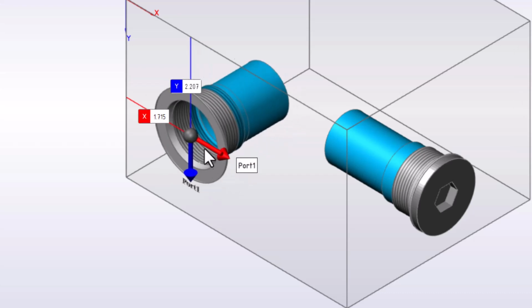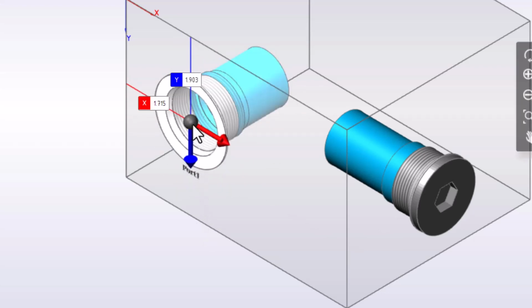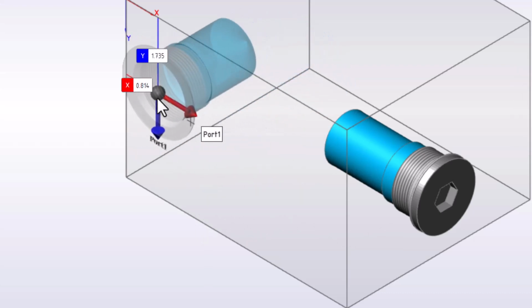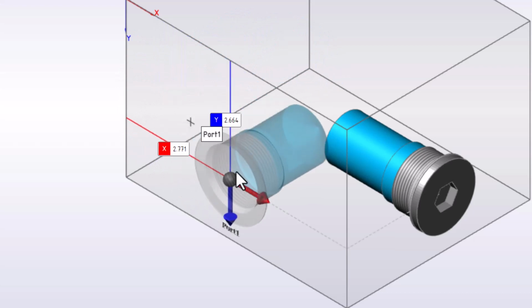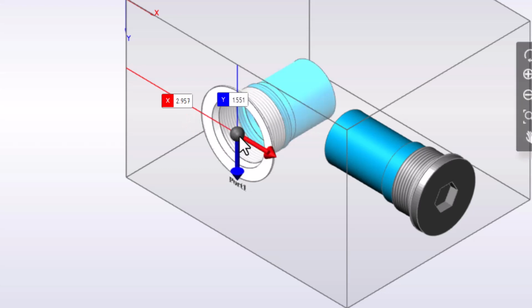Users can move the cavity orthographically in these directions by grabbing the arrows and moving back and forth. To freely move a cavity, users can grab the gray sphere in the center of the cavity and move as desired. Notice the center mark left behind to denote the location of the cavity prior to movement. Once the cavity is dropped in a new location, this center mark will disappear.